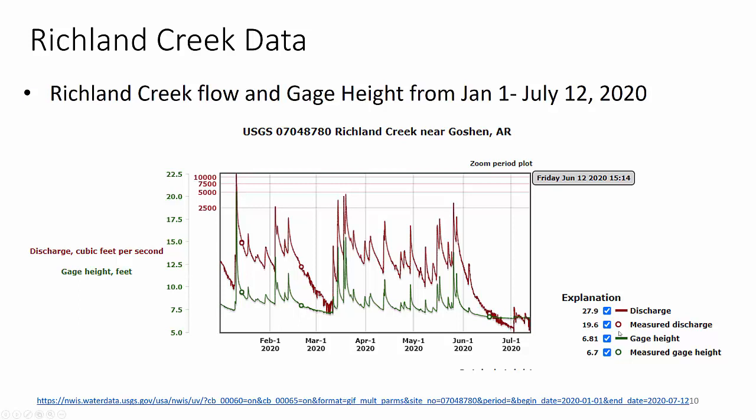We have measured discharges, measured gauge heights, and then we have extrapolated. So these are explicitly measured discharges and gauges. We measure them at the same time throughout the year. And this is a way to make sure that these things are calibrated. We set these up, as we'll talk about later, but we can see that the calibrations are holding pretty true. Now you can see we have a rainfall event, rainfall event, rainfall event, or at least